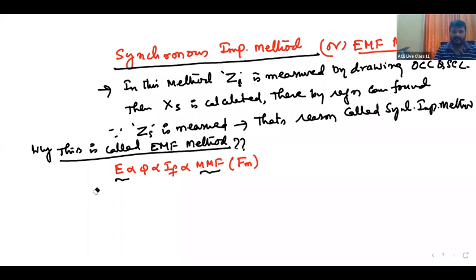Strictly speaking, drop due to armature reaction is a flux phenomenon. It can be represented with field current vector or MMF vector. And drop due to leakage reactance is an EMF phenomenon, because due to leakage flux, self flux, an EMF is induced. It opposes the actual generated EMF.